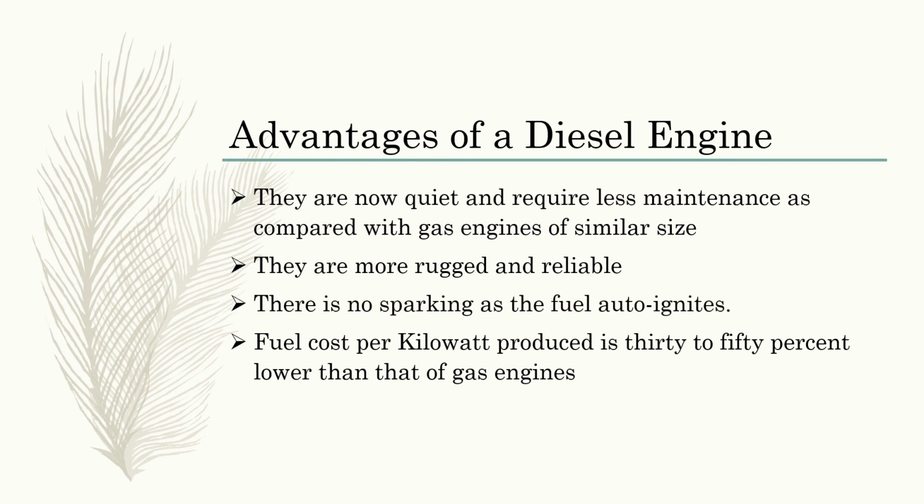Third, there's no sparking as the fuel auto-ignites. The absence of spark plugs and spark wires lowers the maintenance cost. And the last, fuel cost per kilowatt produced is 30 to 50% lower than gas engines. So yeah, very eco-friendly.